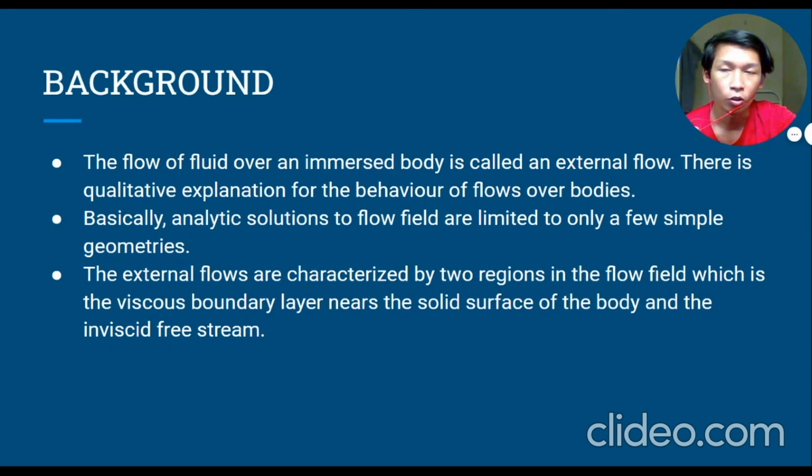As for the background of this lab, the flow of fluid over an immersed body is called an external flow. There is a qualitative explanation for the behavior of flows over bodies. Basically, the analytic solutions to flow fields are limited to only a few simple geometries. The external flow is characterized by two regions in the flow field, which are the viscous boundary layer near the solid surface of the body and the inviscid free stream.